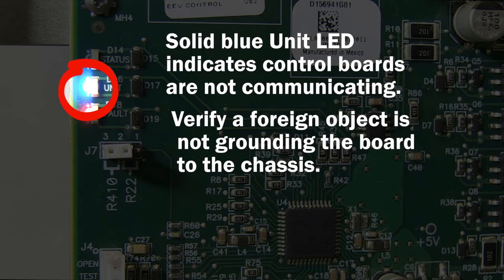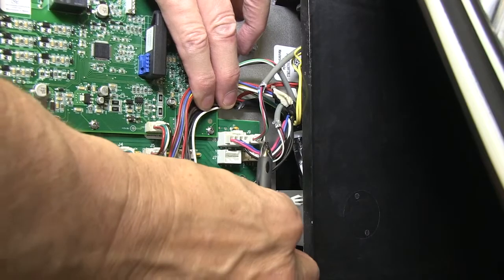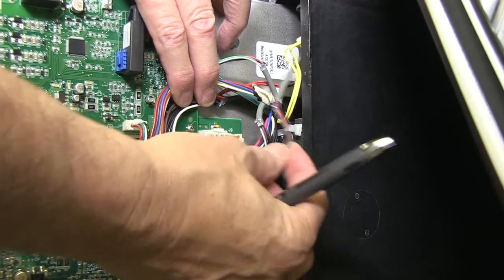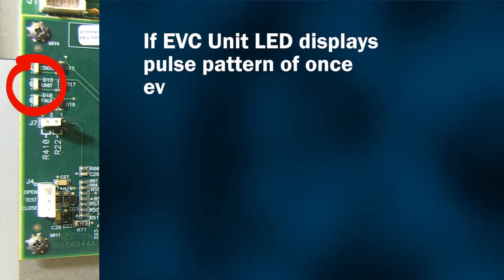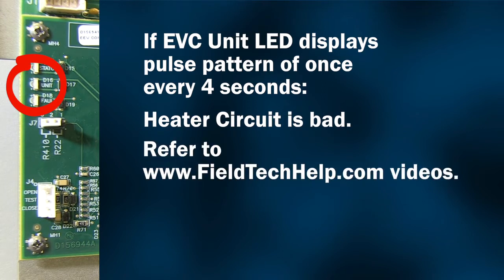Next, we want to isolate the EVC board by powering down the TAM7, disconnecting the heater board, which will be plugged into either J9 or J10 on the distribution board, and then reapplying power. If the EVC unit LED now displays a normal pulse pattern of once every 4 seconds, the problem is with the heater circuit. Please refer to the FieldTechHelp.com heater board troubleshooting video to resolve this issue.